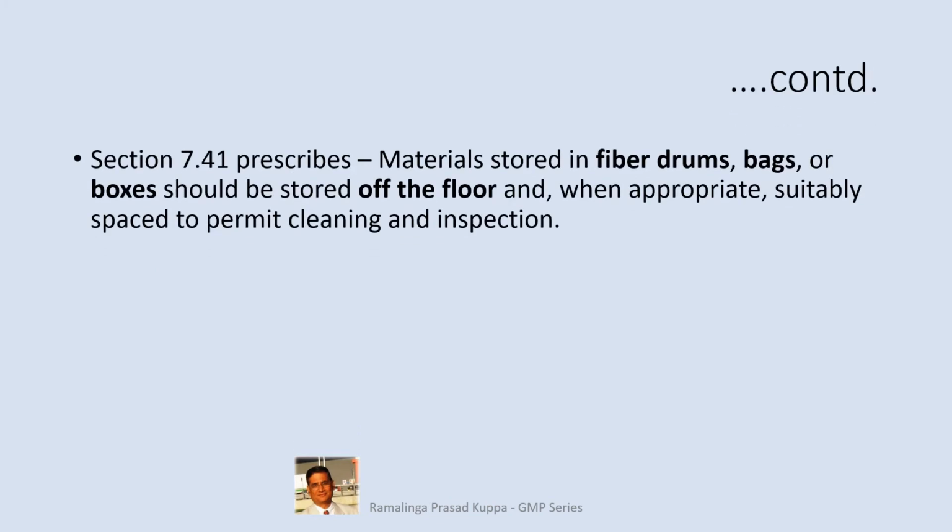Section 7.41 prescribes materials stored in fiber drums, bags or boxes should be stored off the floor and when appropriate suitably spaced to permit cleaning and inspection. This section talks about proper storage. Obviously, when the materials are handled in fiberboard containers and there is accidental seepage of water underneath, the containers could get wet and degrade the material inside.